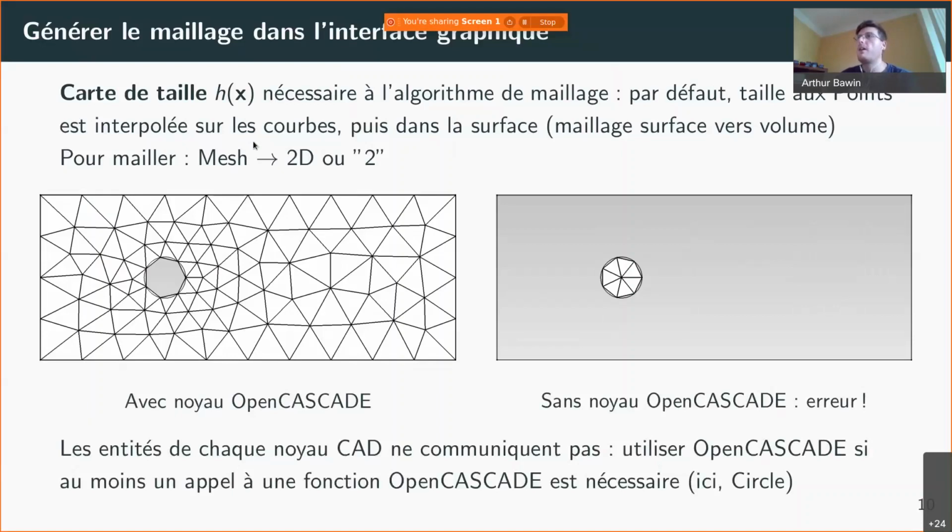And by default, when you specified 1 as the mesh size at the point, since there is no other mesh size available, Gmsh is going to interpolate first the 1 value from the point to the curves, and then from the curves to the inside domain, so that the mesh size in the domain is given only by your 4 points. And I think maybe there's a default size on the circle, because as you can see, it's around 1, 2, 3, 4, 5, 6, 7, 8, 9, 10. There's 10 elements on my line from 0, 0 to 10, 0, so that checks out.